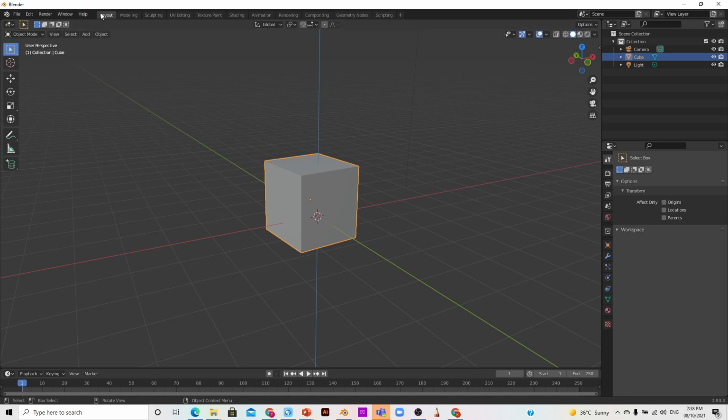Now the layout interface is only for the object, not the proportions. You cannot transform it properly, you cannot model it, but what you can do is change the size, change the direction, you can do so many things, except modeling it. You cannot change this cube into something else until you activate the modeling interface. Now what you need to do is, if you are not selecting anything, click here and then click on edit mode, and that's it, this is activated.